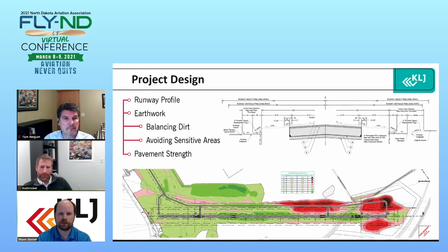We put down a layer of geogrid and then fill in with some of the material in the cut area. So we were going to have plenty of cut area. That way, two things: it expedites the construction a little bit faster, plus it gives us a little bit more uniform subgrade section throughout the whole runway, so we weren't building on one area bad, one area good, one area bad. That way it was uniform, so it should reflect and give us a good